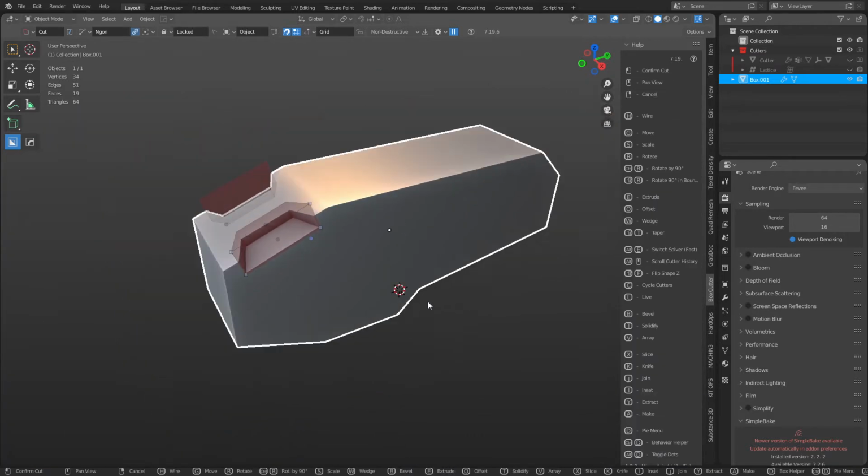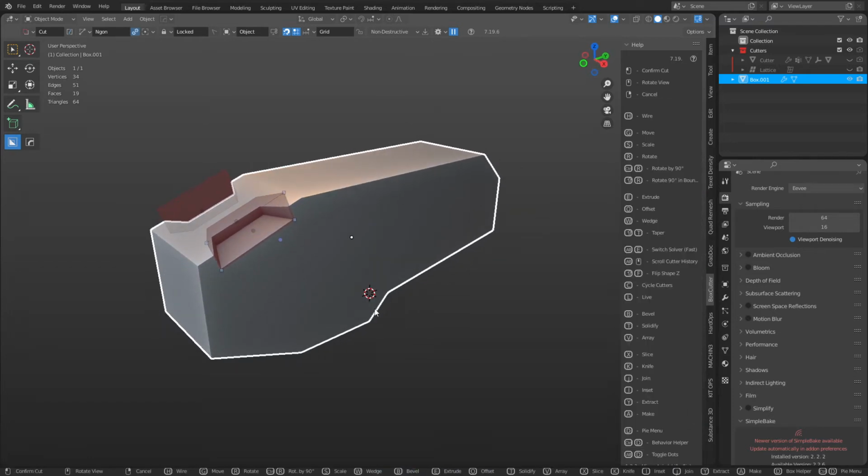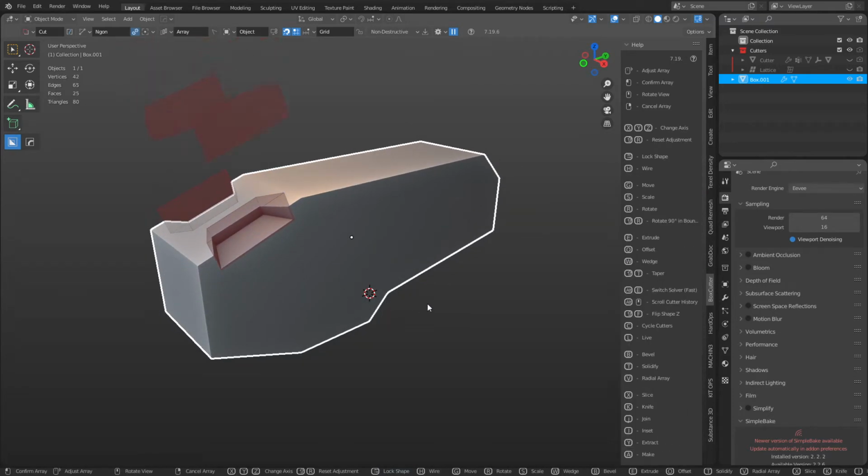All right. There's also ways to do arrays. So if you press V, you'll see we get the arrays going now. You define the axis by hitting the X, Y, or Z. Right? You see how that works out? So I can do mouse wheel up to create more and more arrays. That's something that you might want to consider. Hit V key again, we'll turn that off.